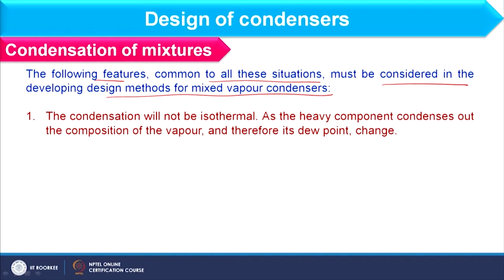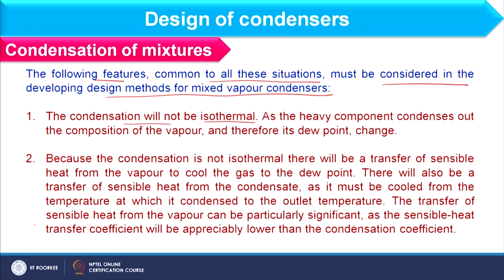So, these points are: the condensation will not be isothermal, as I have already told you. In mixed vapor, condensation is non-isothermal, and the reason we have already discussed. And because the condensation is non-isothermal, there will be a transfer of sensible heat from the vapor to cool the gas to the dew temperature.